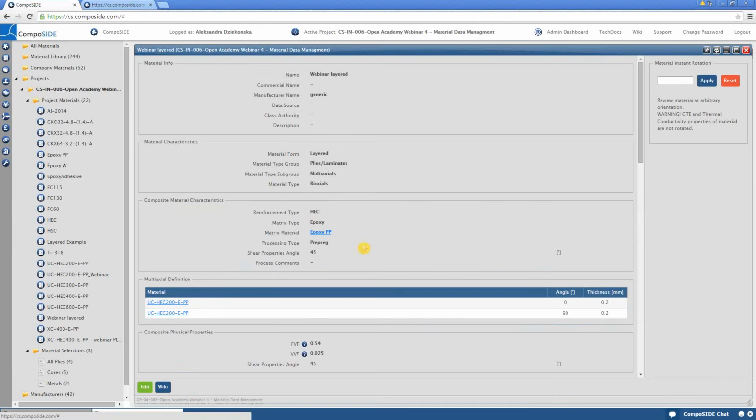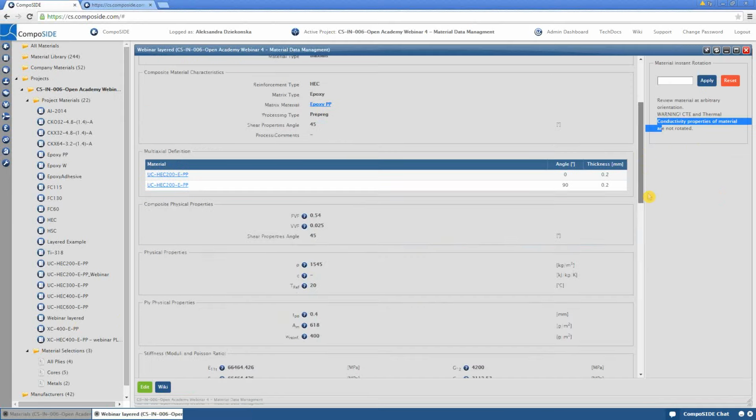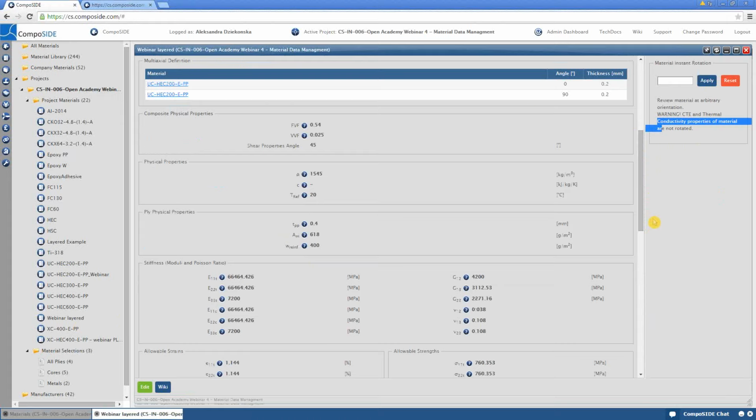So basically, there's a symmetry added to your layup, and the properties are calculated for the zero curvature layup. Of course, when you use it as a part of your full laminate, then the asymmetric layup is taken into account in your full design. But the properties which we have shown you are only indicative and based on the symmetric layup.